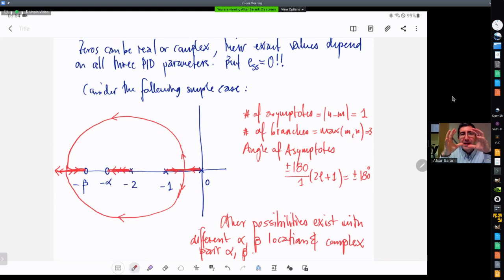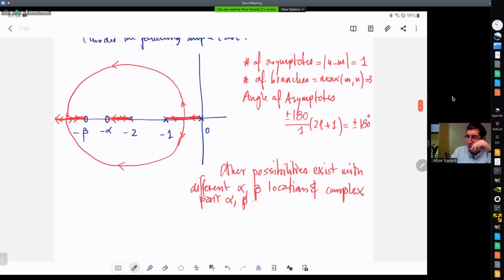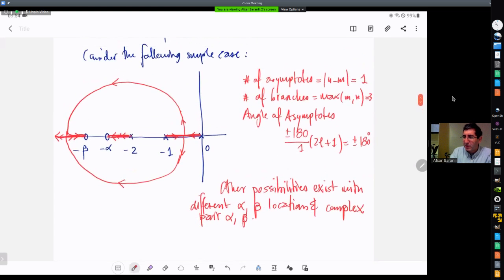Essentially, we can make the steady state error 0, and also we can achieve pretty good root locus performance, because if you take a look at this, this is very similar to the PD controller performance, with the added benefit of 0 steady state error. Okay, you can see that this thing can achieve over here.